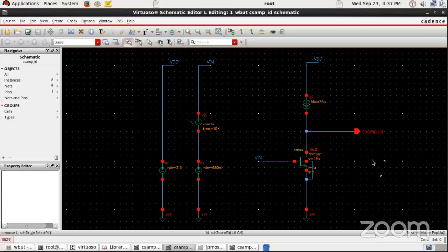And practically there is one more thing. Practically, it is not possible to have a constant current source. Why is the gain shooting up from 22 dB to 49 dB? Because of the impedance provided by this constant current source, which is not an ideal current source. This is not real; it is available for simulation purposes, but in the real world scenario we don't have a constant current source. So we are replacing this with a PMOS transistor.